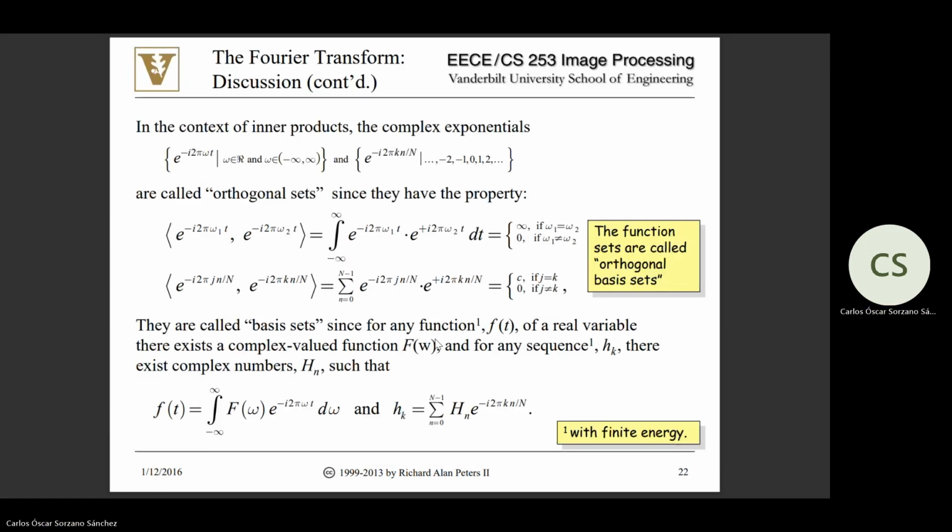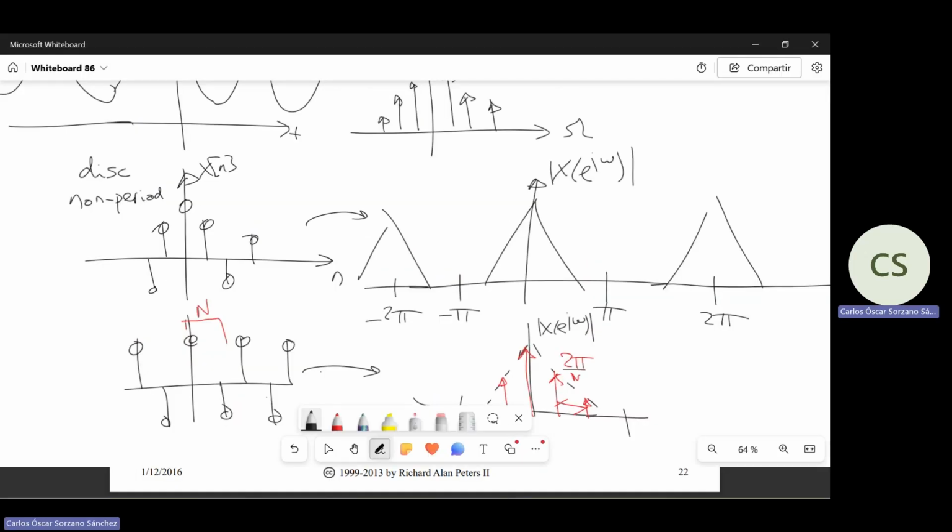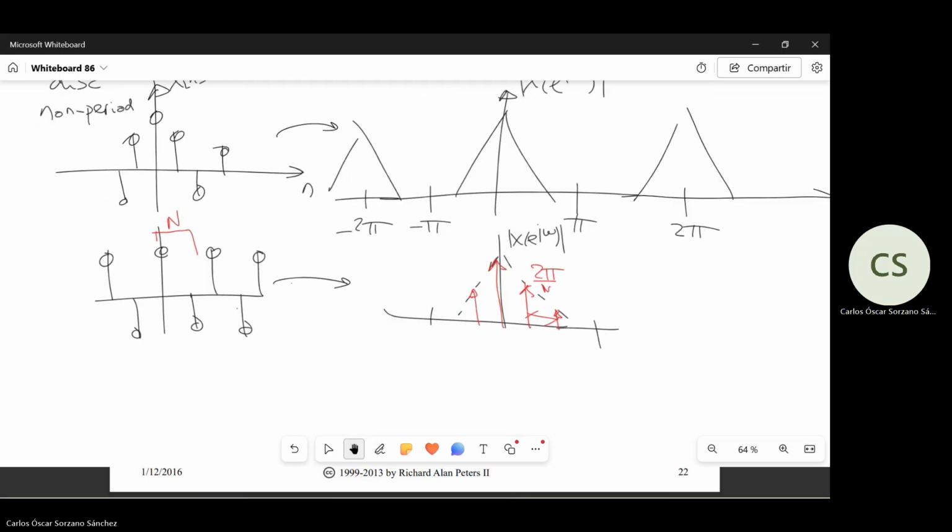So you see that it has defined the basis set for the discrete Fourier transform as 2 pi divided by N times k. So this delta is the one that you get for k equals 0, this for k equals 1, this for k equals minus 1, and so on. Okay, so k is the index of your delta. Very good.